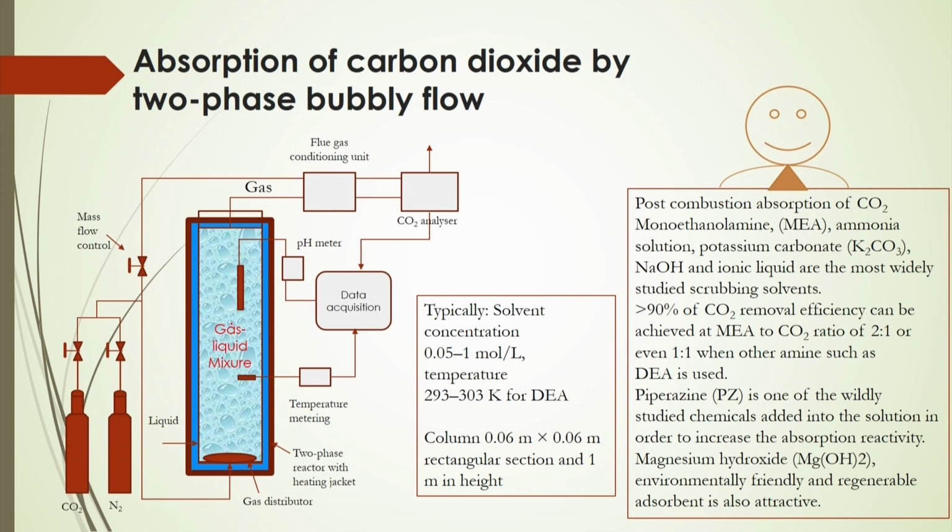Now, if there is a parallel reaction of the carbon dioxide with some other solutions, such as amine solutions, maybe sodium hydroxide, then sodium carbonate or another carbonate form will form in the medium, and you can say that will be reactive mass transfer. In that case also this interfacial area is very important. So, to get this interfacial area, you are making carbon dioxide gas bubbles to get more mass transfer.